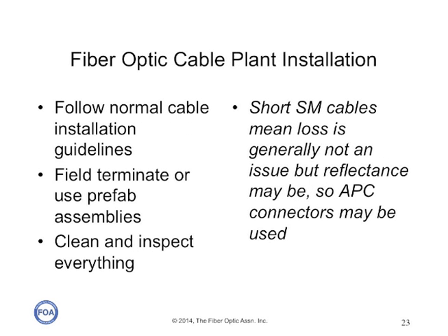Installation of cabling for DAS follows normal procedures for premises or outside plant cables. If fibers are available in the current cable plant, for example, the one installed for the LAN, one can simply patch in the equipment. If new cables are needed, follow the usual installation procedures.